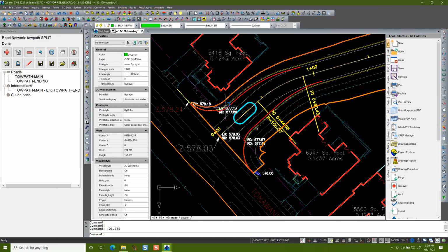But again, if these are 25-foot radius curves, I'm going to have to come up to station 25, because that's where that radius would end, assuming these intersect at 90 degrees. They don't exactly, but that lends itself to all kinds of additional complications.